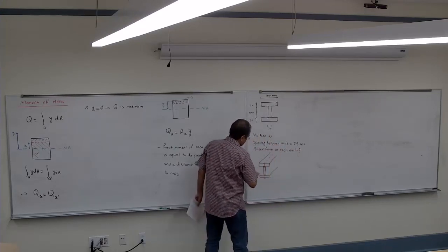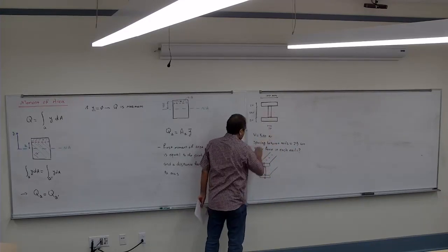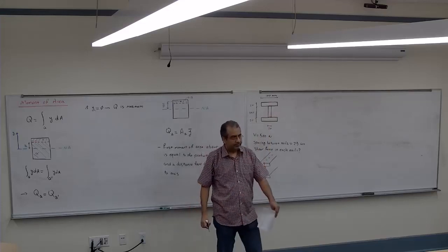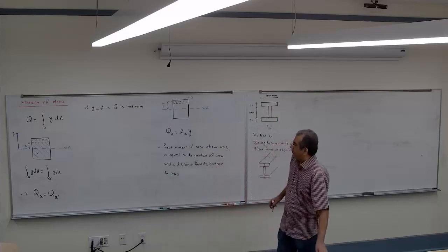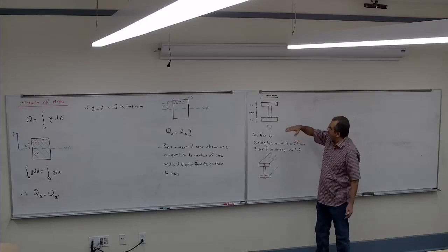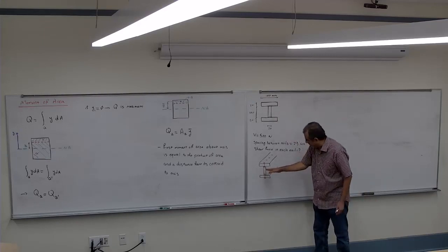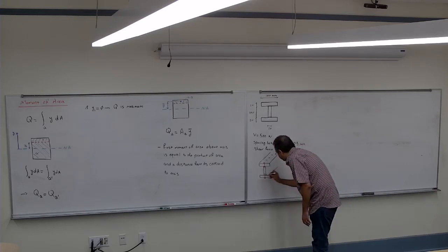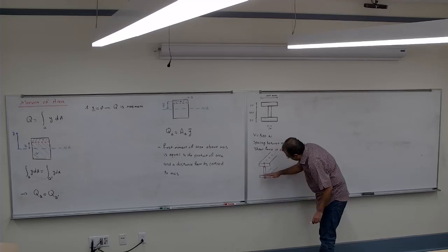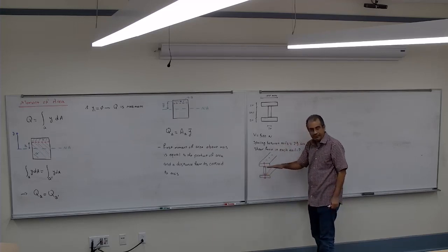So look at that. There's a shear force horizontally, correct? At the interface, there's a shear force applied at the interface. Listen here very quickly. The shear force is applied at that plane, so that's where the shear happens, horizontally between the top and the middle, or the bottom and the middle. It's going to cut it there.